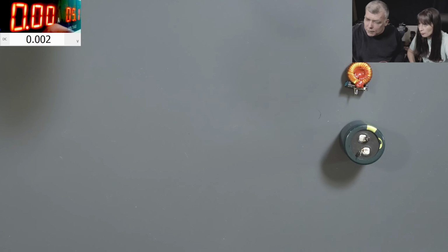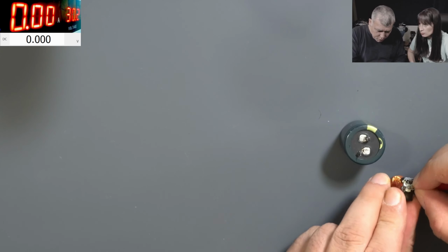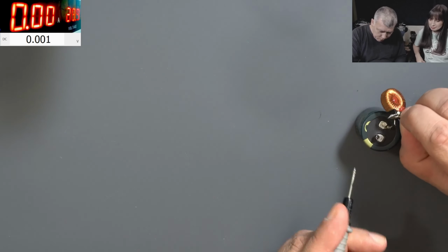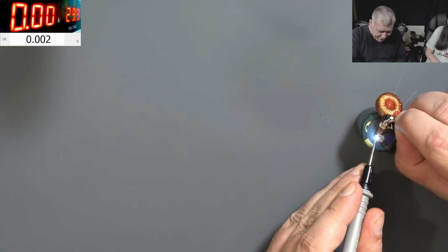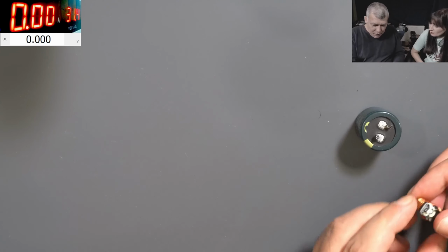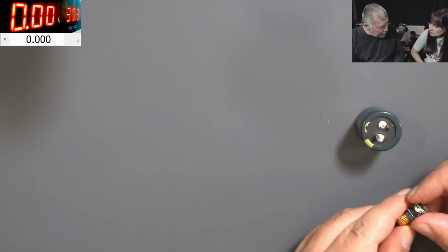Now the MOSFET is switching. It's charging the capacitor, it's charging the coil, so plus and minus. Check spark. There. You see the spark? So even if the capacitor has 5 volts, that doesn't matter. Because the MOSFET is switching 12 volts, right? So when you come with 12 volts on one side of the coil, on the other side you have 5 volts from the capacitor.